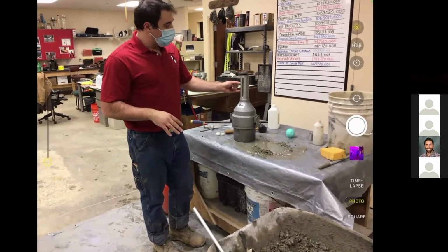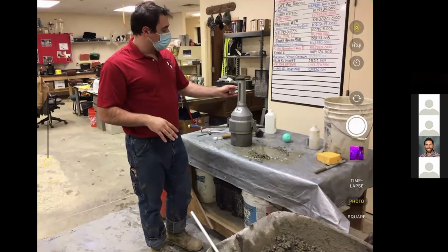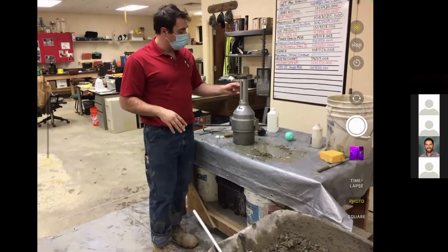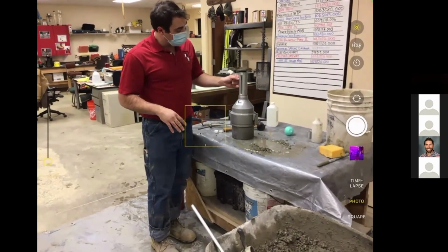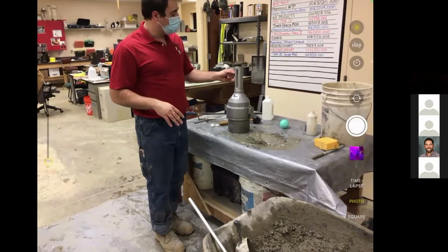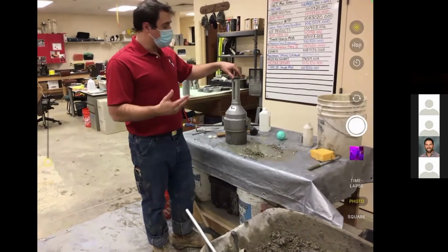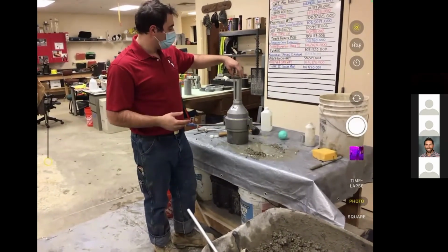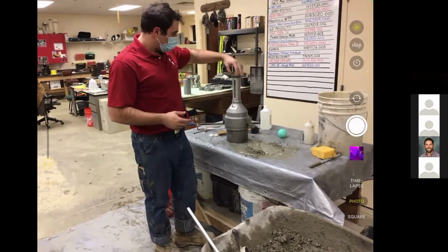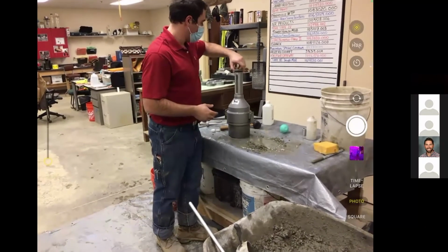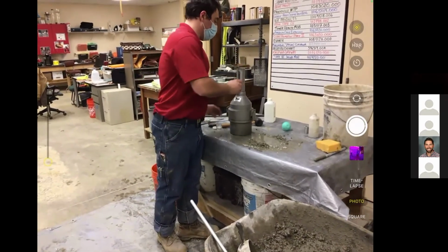If we did not add enough alcohol, it could result in excess foam. If we see more than 2% foam in our glass window here, the test would be invalid. We'd have to repeat the test all over again. So assuming that in this demonstration everything went right, we would have our final reading.